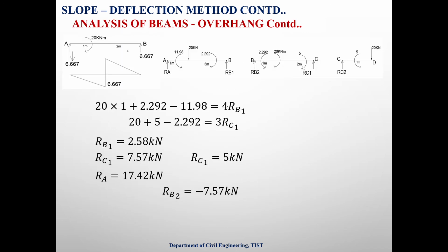Then find out the support reactions. After getting the support reactions, mark all the upward values in the upward direction and all the downward values in the downward direction and complete the shear force diagram.